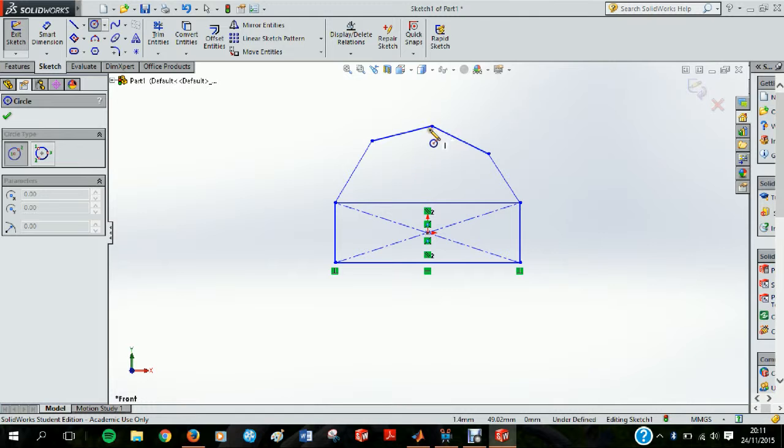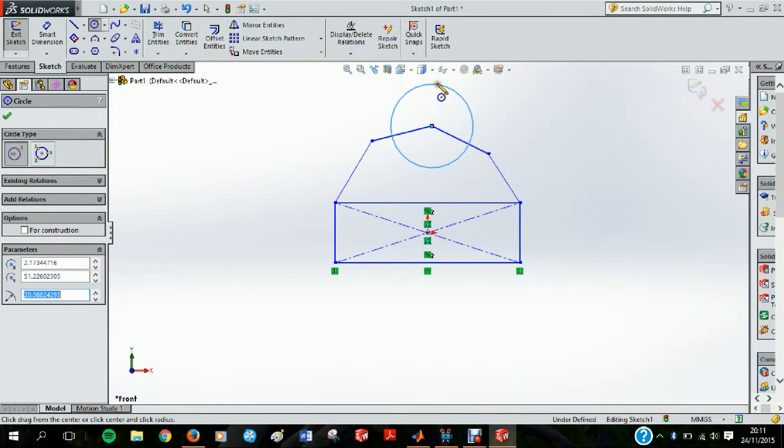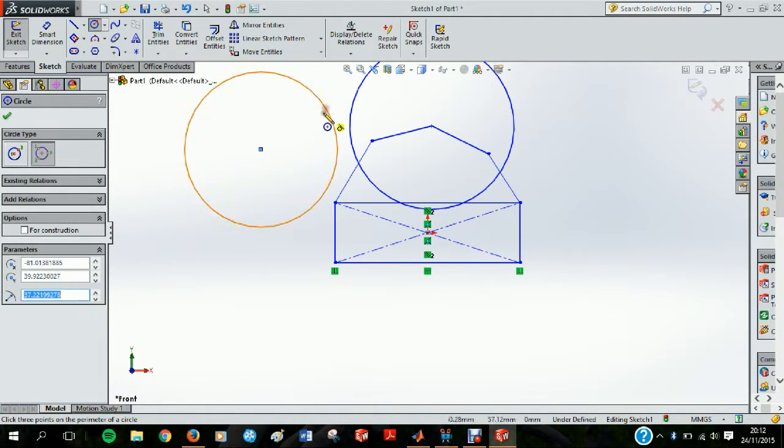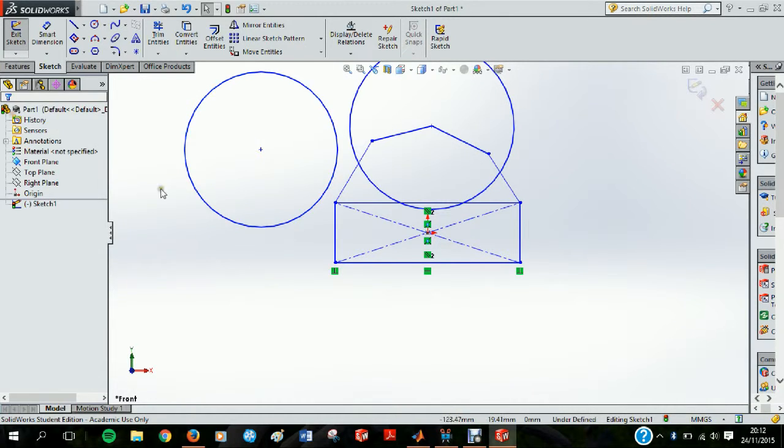Another function is a circle. Here, in this case, we're going to work from the center point to a point on the radius. And using the toolbar at the left hand side, we can change the radius of this circle. This next function is how to draw a circle with three reference points. This can be useful when trying to draw a circle between three different tangent lines.